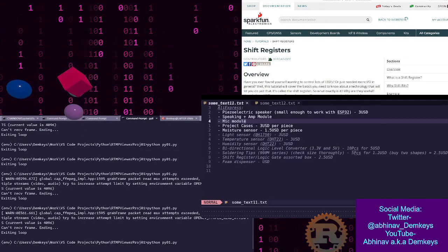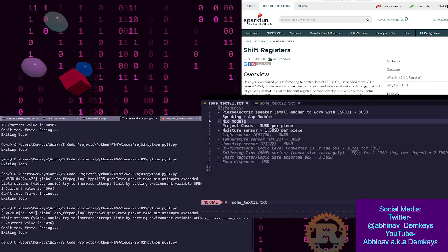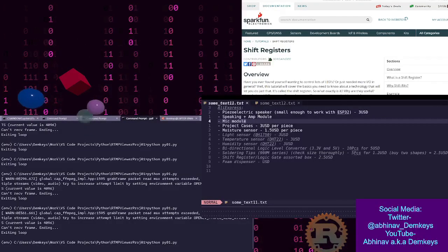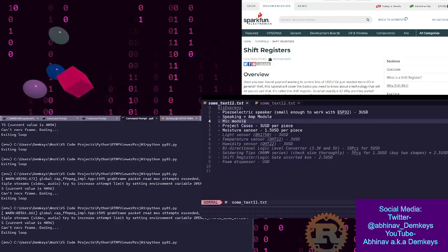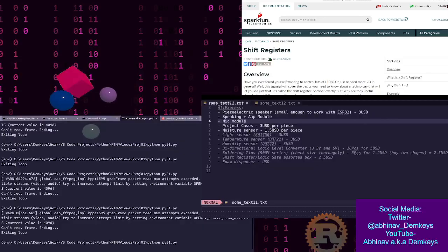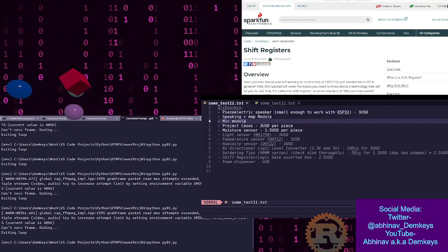Here's the breakdown of why, addressing your points about powerful CPUs versus microcontrollers in robotics. The two brains of a modern robot. Okay, this is interesting. Most sophisticated robots don't rely on a single type of processor. They use a distributed computing architecture, often with two distinct levels. The high level, the brain, which uses a CPU and GPU.